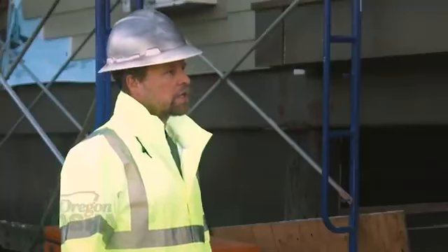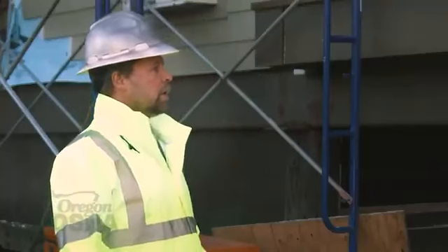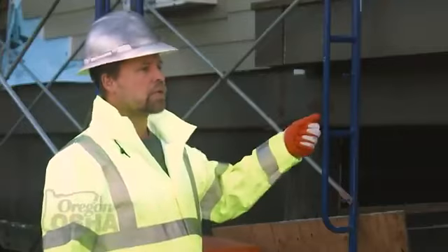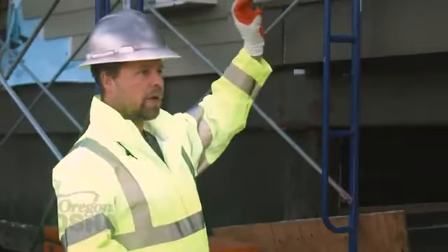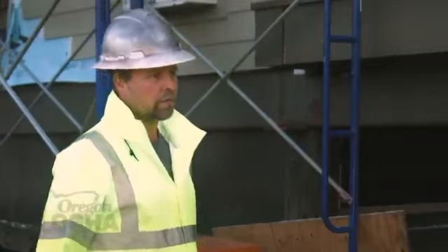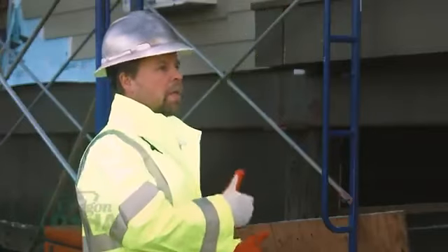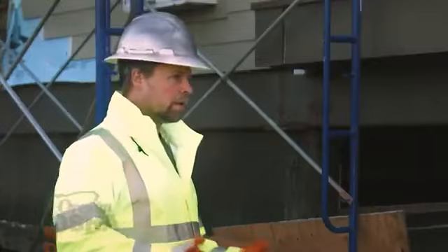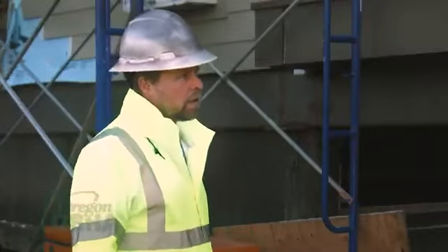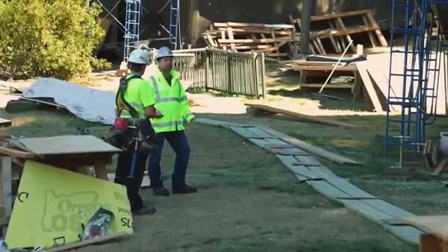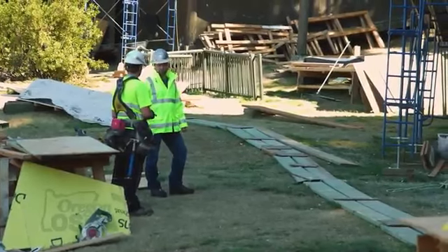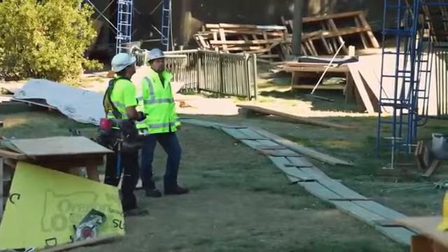Sometimes you have to change some of the connections to the wall due to the work performance, so you want to attach at another point. How do you anchor and secure the scaffolding to the building? At no point do you want to make it any less structurally safe to use. Each crew has a supervisor, and you want to make sure that everybody's engaged in the safety process.